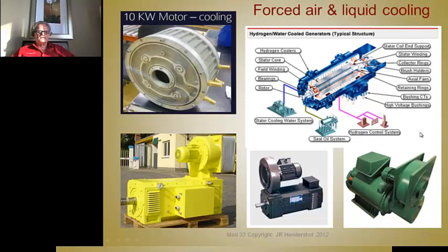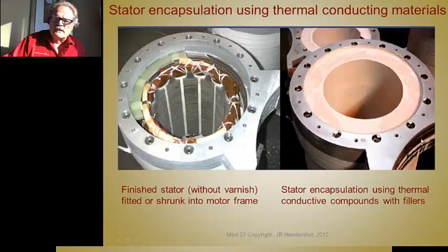Now here's an example of a very large machine with hydrogen coolers, stator core, field windings, bearings, rotor, high voltage bushings, and retaining rings, axial fans, brush holders, collector rings, stator winding, stator end ring support. This looks like a synchronous generator, with a stator cooling water system, seal oil system, and hydrogen cooling system. Serious cooling is required on big machines with long diffusion paths to get the heat out from the sources.